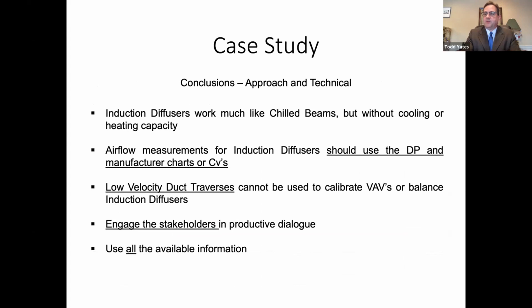We measured the differential pressures, and then when we were done with that area as a confirmation, we could dump these VAVs and get a total flow that we'd calibrated using the differential pressure, and then compare a traverse to the larger branch that was at a much higher velocity, and we had very similar readings. We didn't show a lot of duct leakage. We didn't show a lot of difference. So that confirmed that we were on the right path with this.